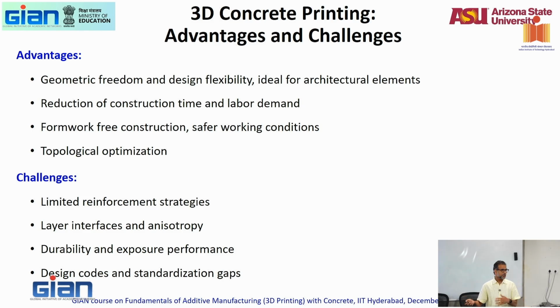Topology optimization, you can optimize in whatever way you want. Challenges: limited reinforcement strategies. Conventional concrete gives you so much there. You put the steel, pour concrete over top of it, you're done. But now when you're printing, how do you put rebar along with it? That's a challenge.